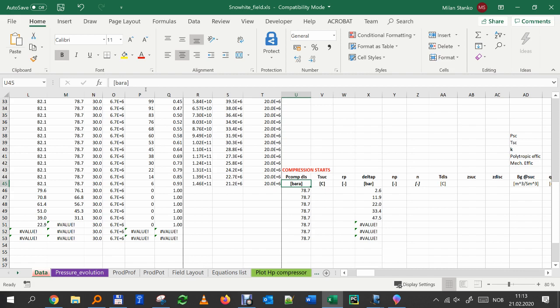So you see, discharge pressure doesn't change, because on that line I always have the same rate and I always have again separator pressure. So that pressure remains constant. But the available pressure at the suction, which is this one, is going down with time, because reservoir pressure is going down with time. Okay? And the delta P of the compressor is here. Okay?